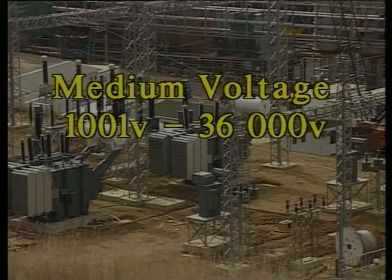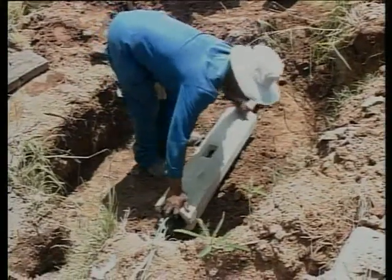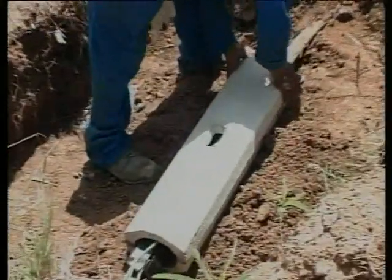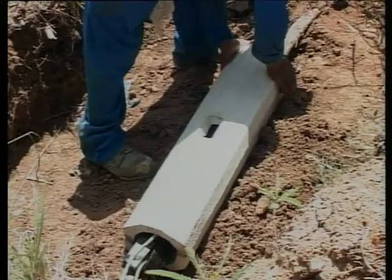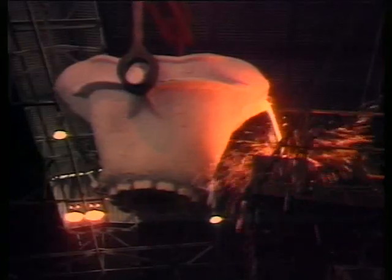Medium voltage is classified as any voltage ranging between 1001 volts and 36 kilovolts. The majority of medium voltage cabling is used in reticulation systems through underground routing to substations. Certain heavy industries require medium voltage supplies, especially in mining and smelter operations.